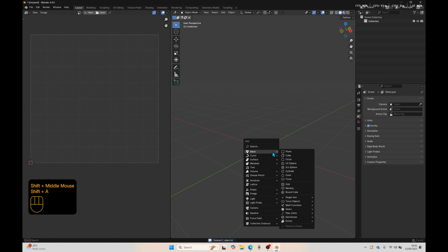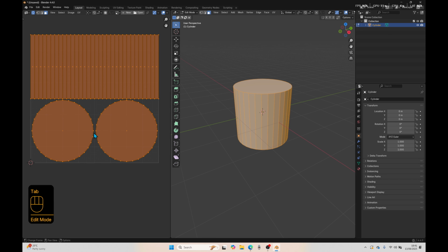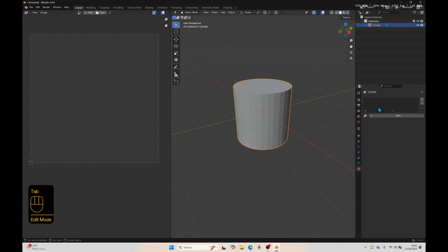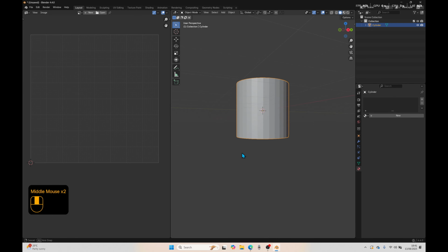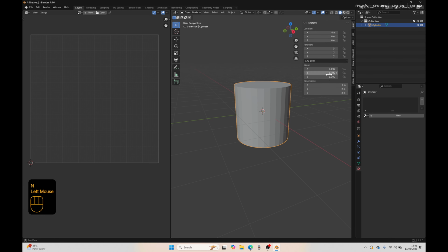We were going to create a barrel. So if I just bring this cylinder in, we already could say that that is a pretty good barrel, okay? It comes unwrapped. We can add a material, because in the last lesson, I showed you how. But we want to add a texture to our material now. So before we do that, we want to make sure that our mesh, our object, our asset is the correct scale. It looks right. Because if we look at the scale of this, or the size of this, the scale is 1, but the size is 2 meters up and down, 2 meters in dimension.